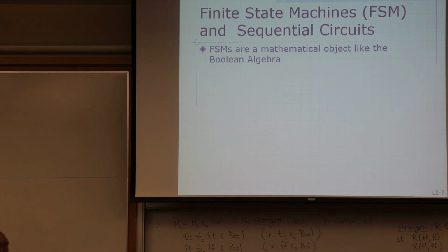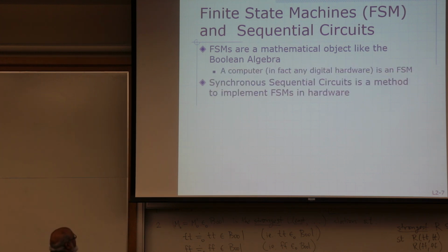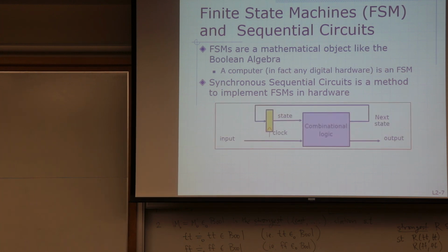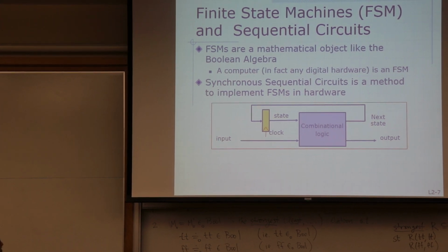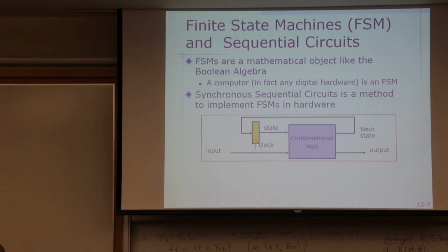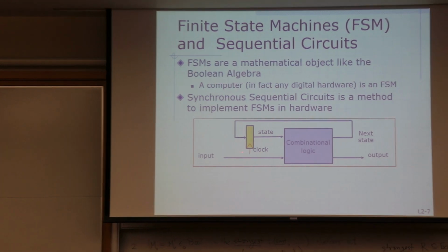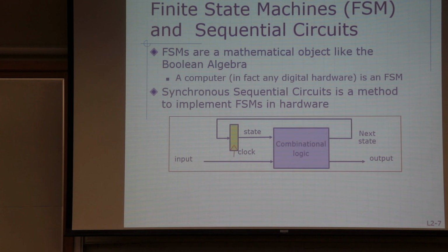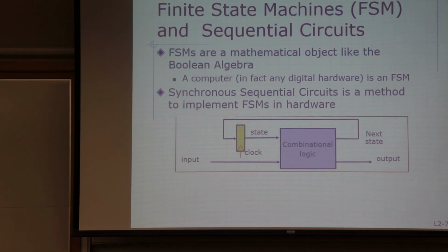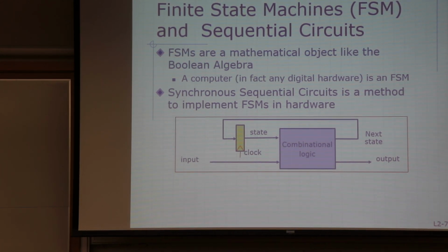So when I say sequential circuits, to be exact, what I mean is synchronous sequential circuits, a method to implement FSMs in hardware, and usually it's drawn like this. The way to read this is you have some state elements, some storage here, which can only be updated on this clock. So clock is very regular, it just comes.